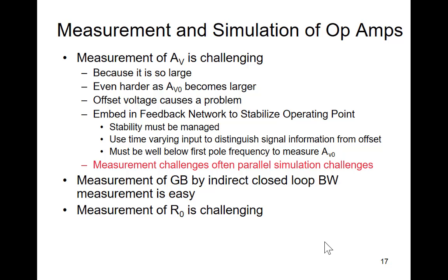That only works with single pole amplifiers. Almost all of our amplifiers are going to be dominantly single pole. We will compensate them so they look like single pole. We will see why we do that later. So what if the load was reactive? Pardon? So if the load was reactive, then this wouldn't apply? I didn't put a reactive load on. Yeah, it just wouldn't apply if I had a reactive load. Right. I get a different equation. And by the way, it won't overcome the problem.